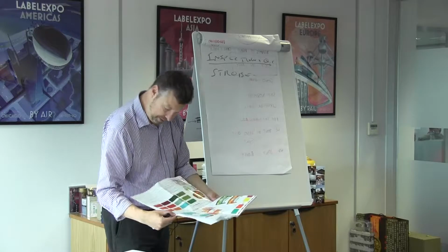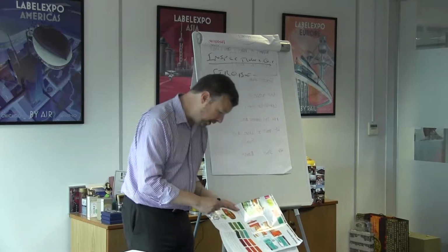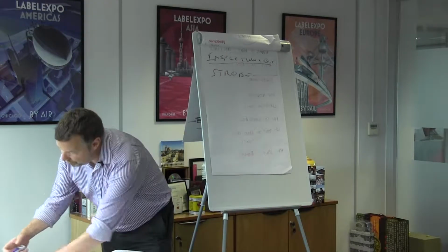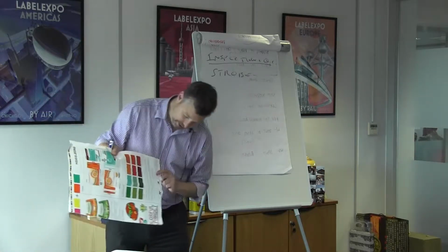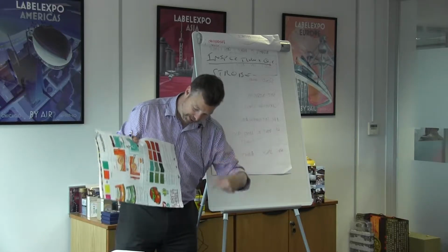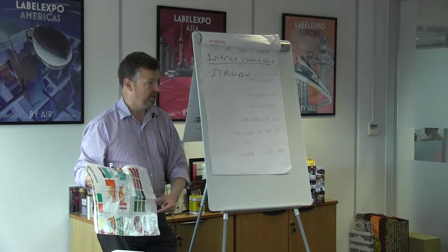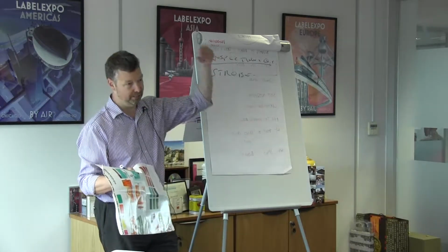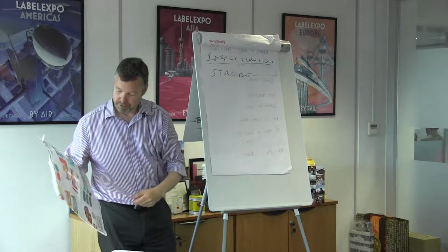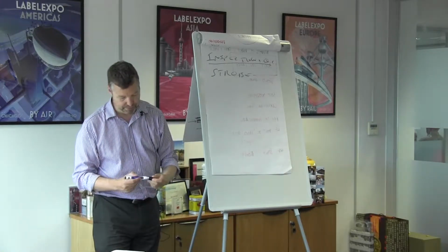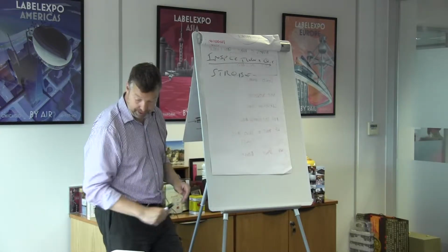You have a web of labels and you can't quite see it. I don't think I've got any here, but on the margin of the label, they'll print registration marks, which are normally just kind of crosses like that. So what the camera's doing is, every time one of those passes, it's measuring it. Providing that measurement always stays the same, the cyan will always land in the right place on the magenta, and the yellow will land in the right place on the black. So that's basically making sure all the plates are aligned and everything is lined up.